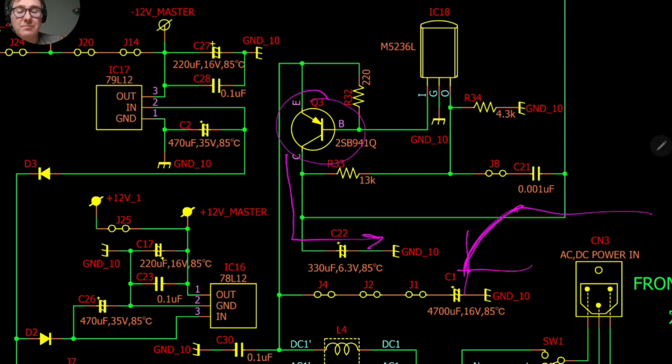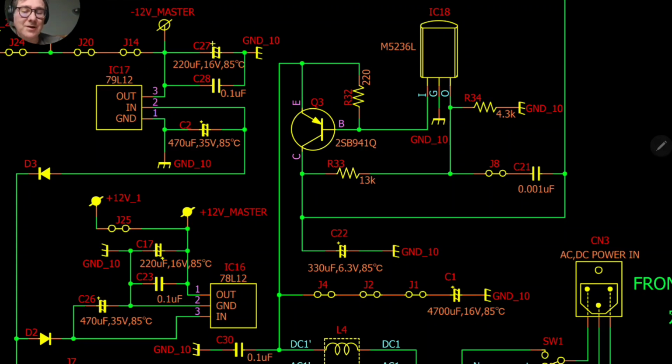This is a problem. More or less, if the machine was new, I would say, yeah, it's fine, you are over 5 volts in here, there's no problem. But this machine is close to 40 years old, almost. And things are not that perfect, and this is a little bit problematic. So there's a lot of stress on this capacitor. Of course, the machine was not designed to still be working after 40 years. But anyway, we want this machine to work for many years from now on.